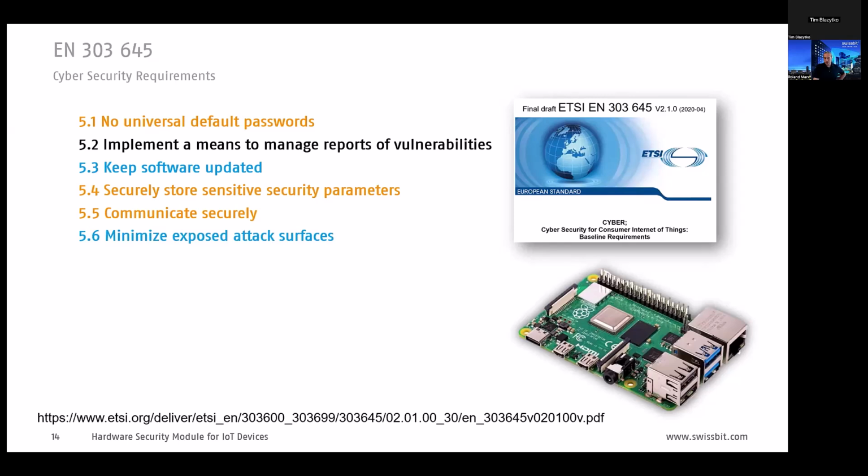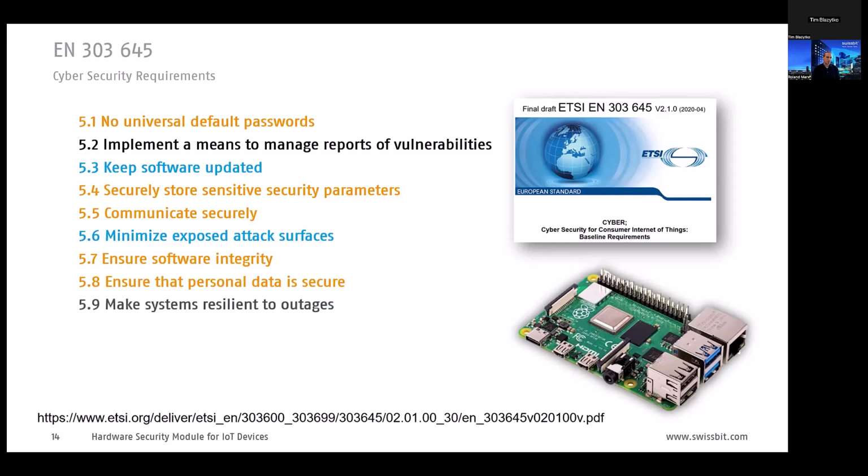Minimizing the attack surface mainly also means, like Tim said before, if you can just dump the flash, then this is the first thing how reverse engineering can happen. If you somehow prohibit that the flash can be read out, and there are methods for that in normal chips, but also for eMMCs and micro SD cards we have the same things, but with another mechanism like our flash controller that can protect the data there. Software integrity and so on, so that some things cannot be changed. Tim also showed that, changing not to an equal. These things should be visible if somebody changed it, and then actually the system should not boot anymore. So this would also be an integrity mechanism, also called secure boot.